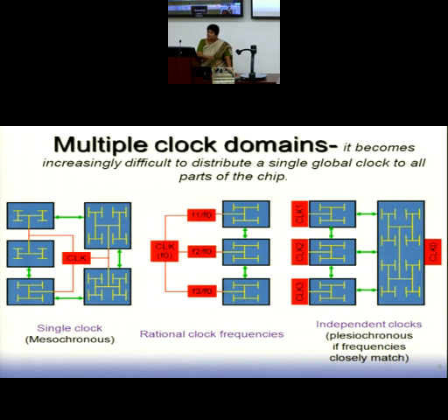Now, lesser than this problem is a synchronization error. Error means the system is not going into an illegal state. Maybe it so happens that it is interpreted wrongly, but it still comes to a valid state, which is a known state. It is not an illegal state. But because it is interpreted wrongly, the value should have been 1, you are getting a 0. But it is a consistent thing. All blocks are behaving consistently. So this is known as a synchronization error.